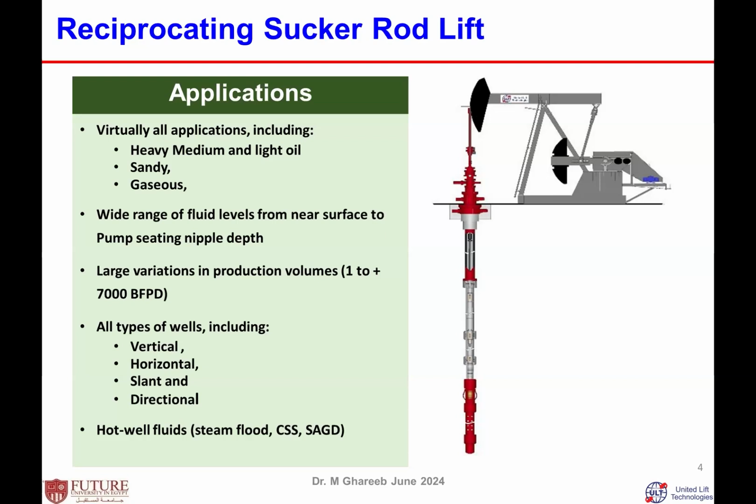Sand, yes, if there is sand, and gas the same, but all of that needs some special design. Especially if I use very heavy crude oil, then the downhole pumps and equipment should be selected for that condition. Sand is the same. If a well is sandy, they have to select the right downhole equipment to handle sand. In some areas, especially in the Middle East, if the well stops, you find 2, 3 joints above the pump full of sand. That means the pump is lifting a very high quantity of sand. The same goes for gas, meaning a very high gas ratio.